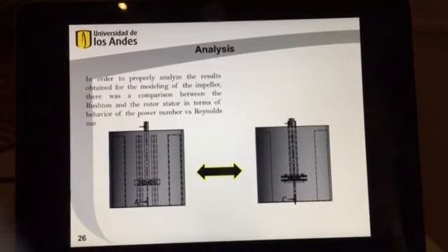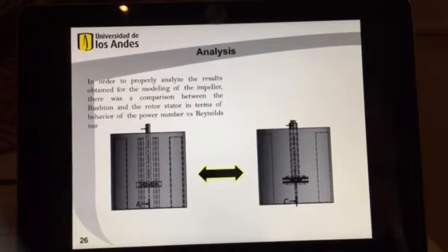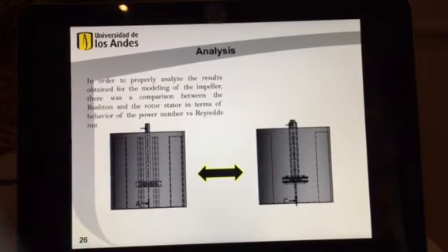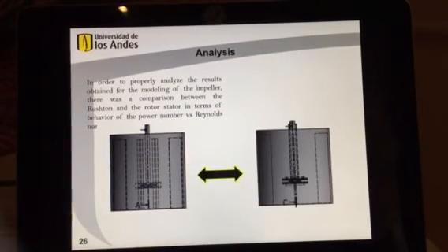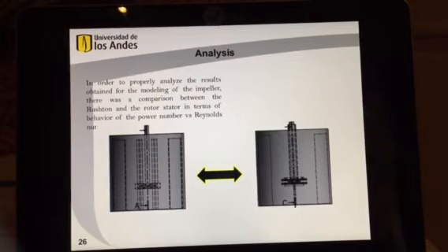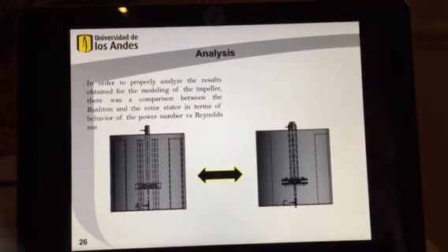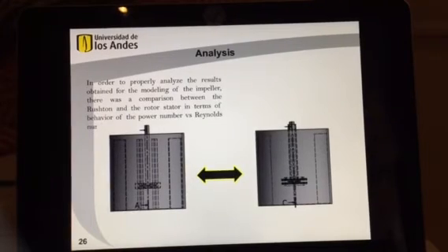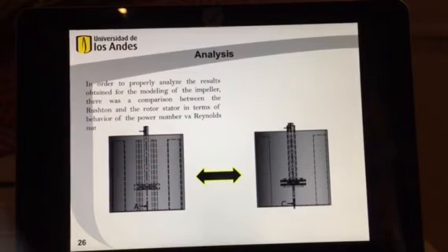For the rotor stator, there is a representative difference, especially in the laminar regime, possibly because of the low rotational speed supplied. The torque is not detected with such severity, and in consequence the power is too high compared with the needed. But most important, the models used to describe this phenomenon are the simulations, because all of them were made under the same K-epsilon turbulence model.